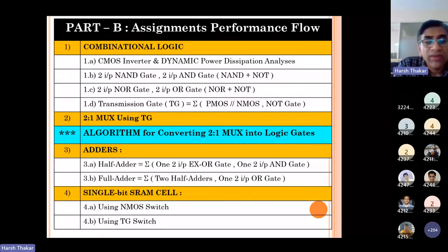So basically, for making one full adder, I need 62 MOSFETs. Now 62 MOSFETs needed to make one full adder is not an economic utilization of transistors, at least in VLSI, because the branch of VLSI aims at achieving a digital functionality with as minimum number of MOSFETs as possible. So this is not going to work.